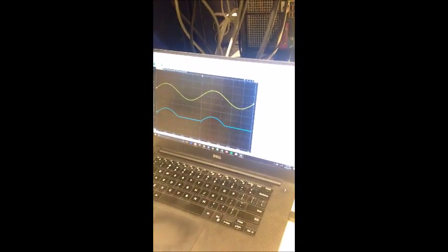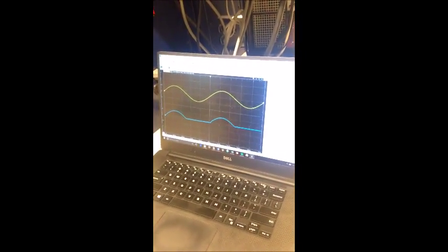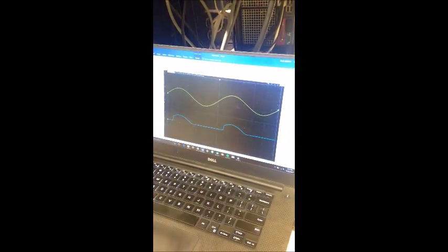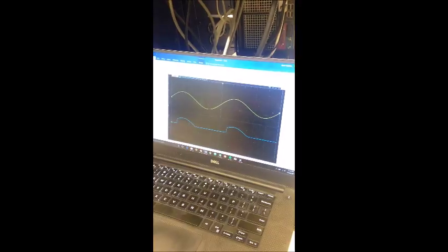Because if you were to run it straight through the diode, like we do in A or B, you have a voltage drop through the diode. And then another interesting thing is when you increase the frequency. So I just have a screenshot here. When you increase the frequency, you get a much higher slew rate, which just comes from the qualities of an op-amp essentially. So I think that's everything for part C.